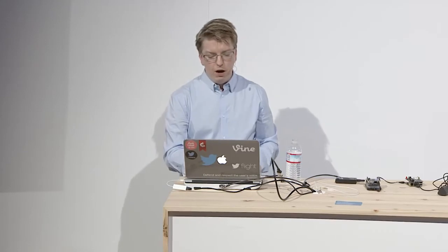We're listening to those messages I've just shown you. And then, as those individual messages come in from those individual sensors, using JavaScript, it's pretty ugly, as JavaScript sometimes can be, I'm parsing each value and putting it into a tweet. And then I'm telling it to tweet no more than 10 times an hour, so I'm not going to bust any limits. And hopefully we'll see right here that 35 seconds ago, we actually tweeted from our Pi through that proxy Node-RED the current information about what's going on here.